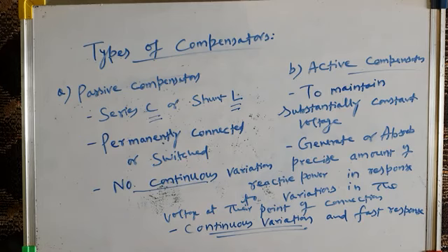Then we found that there is a need for compensation, and if you do the compensation, for example load compensation or system compensation, the reactive voltage drop because of the reactive component of the current gets nullified by the capacitive reactive voltage drop.